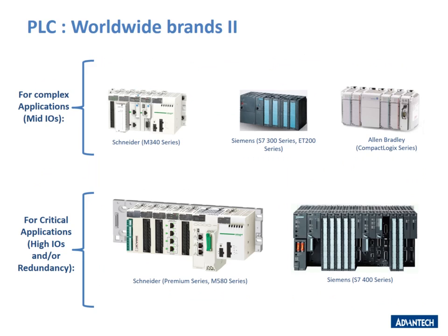On the other hand, for more complex applications with a middle number of inputs and outputs, we can find controllers such as Schneider M340 series, Siemens S7 series, and Allen Bradley CompactLogix series. Finally, for critical applications that require a high number of inputs and outputs and redundancy, we can find Schneider Premium series and Siemens S7 400 series.